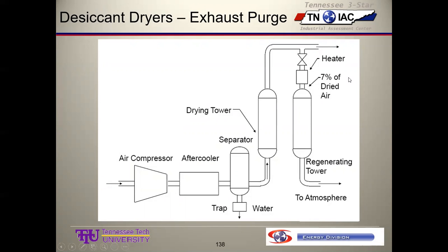Now, some people take waste heat from a boiler stack, blow down, something that you're throwing away, and pipe it over and put a heat exchanger in and heat that air with waste heat, in which case that's it. You don't have to pay any more than for the 7% of the rating of the dryer. Another thing to consider, these percents are of the rating.